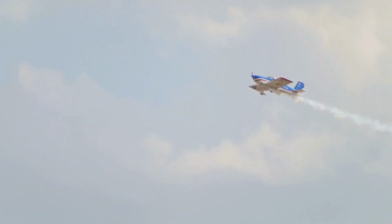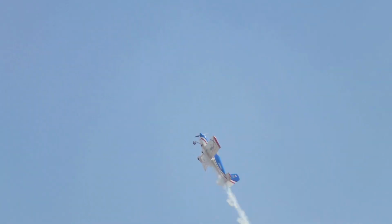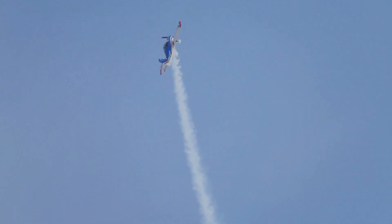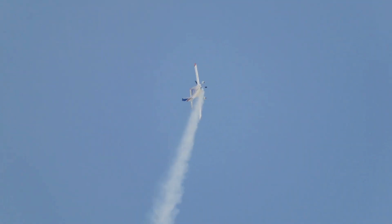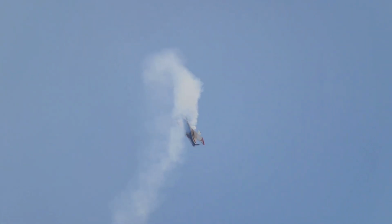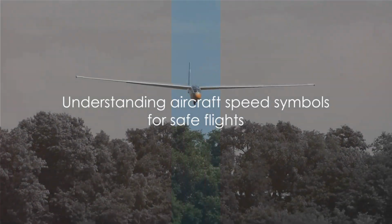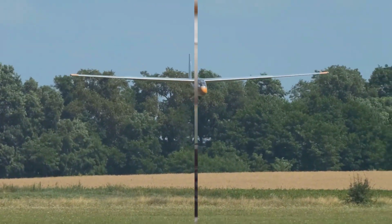VLO is the maximum landing gear operating speed, the maximum speed for extending or retracting the landing gear. Lastly, we have VLD, the lift-drag speed, which corresponds to the maximum glide ratio. It's the speed at which you can achieve the greatest distance for each unit of altitude lost, particularly important in engine-out scenarios. Understanding these speed symbols is key to ensuring safe and efficient flight operations.